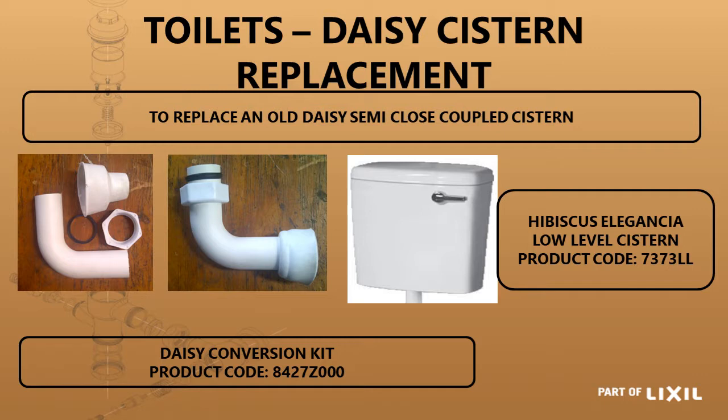If we have a look at some components that can be used as replacements. Now the old Daisy semi-closed couple suite used to have a rubber flush pipe. The rubber flush pipe doesn't exist anymore. So what we do, we've got a PVC flush pipe together with the necessary connections that can be supplied as a replacement. So that is called a Daisy conversion kit.